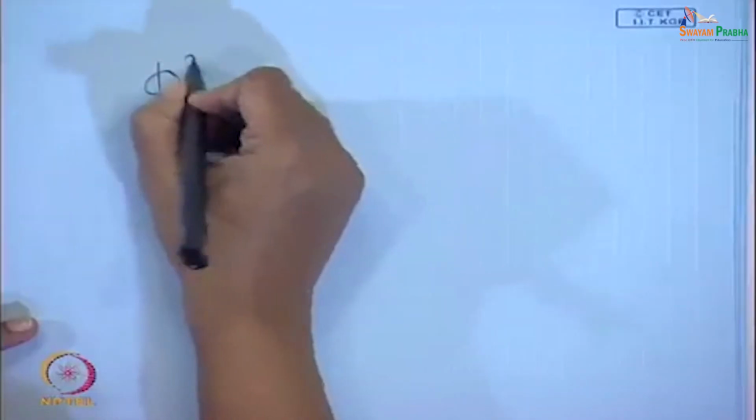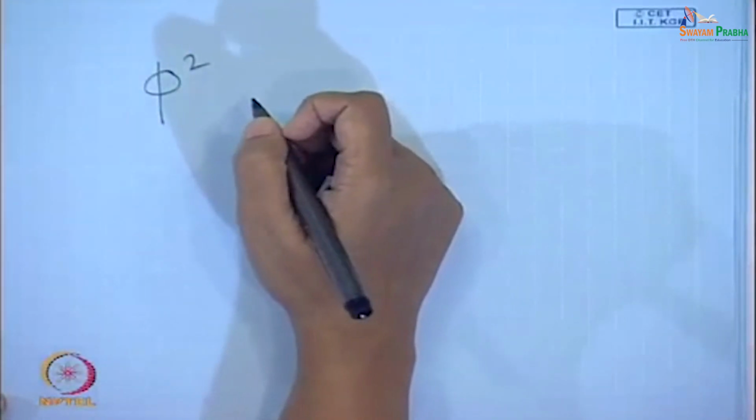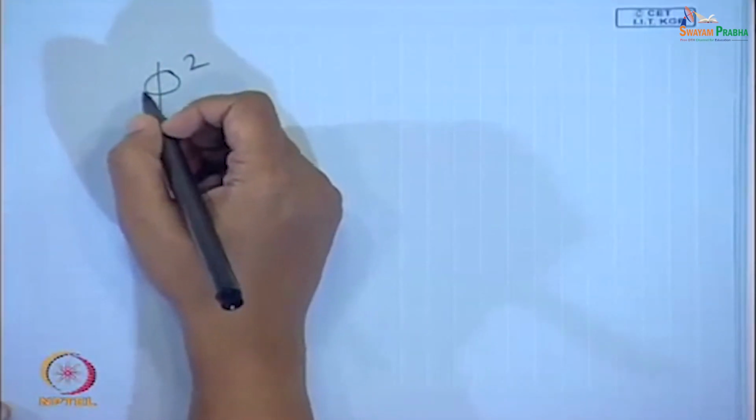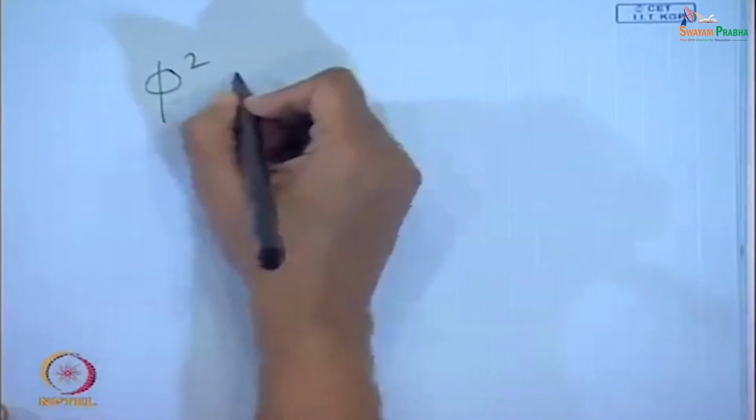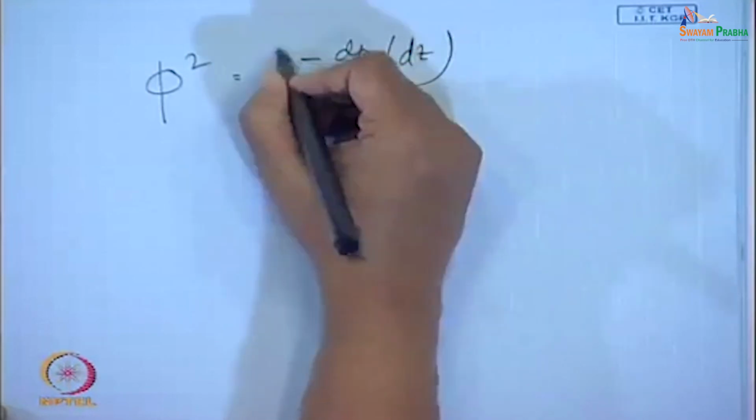One is by a suitable definition of the friction factor and the other is by a suitable definition of the correction factors. These correction factors are defined in terms of phi square. These are known as two phase multipliers, and they simply relate the two phase friction factor dP dz frictional.